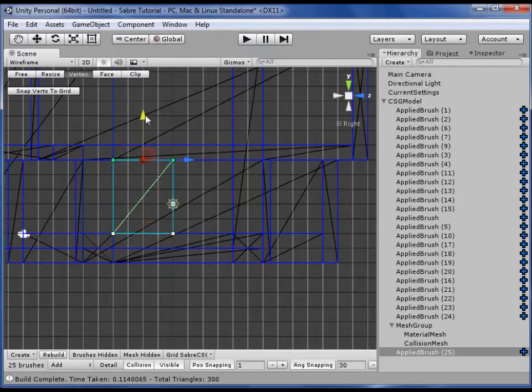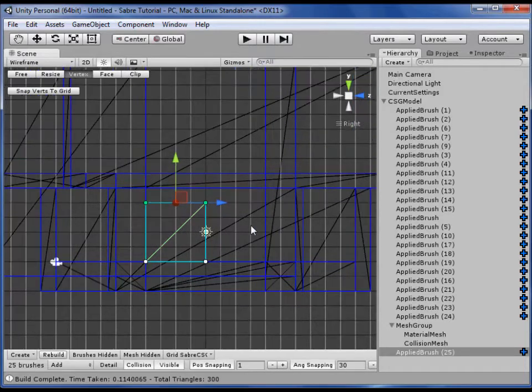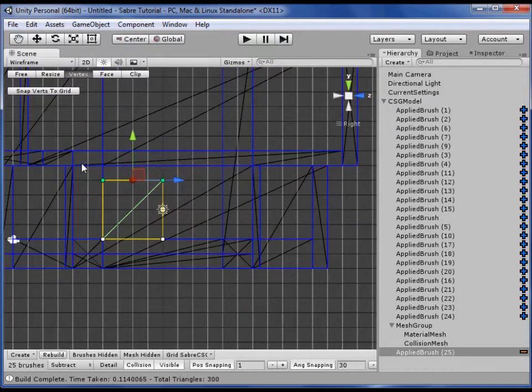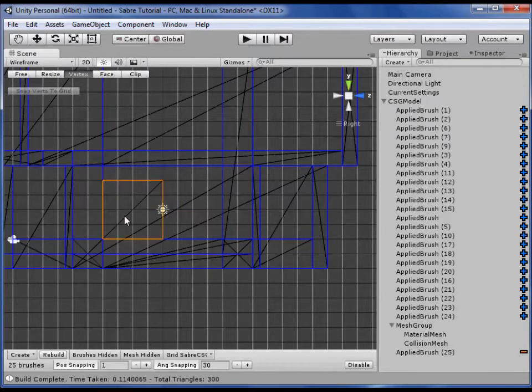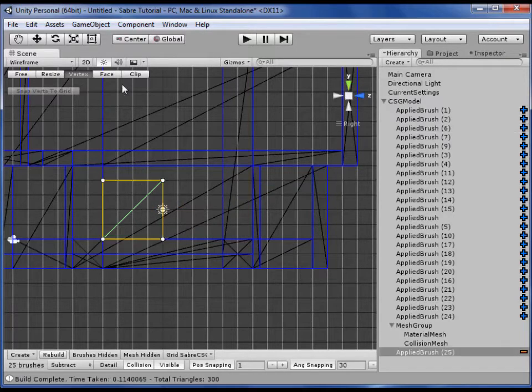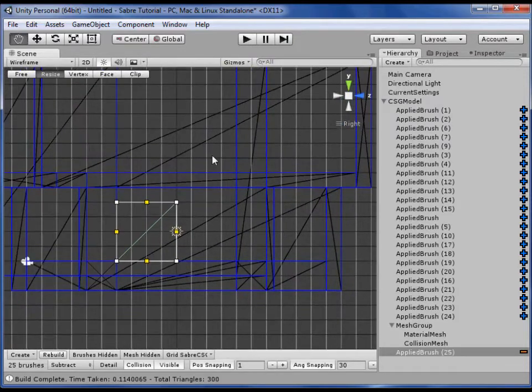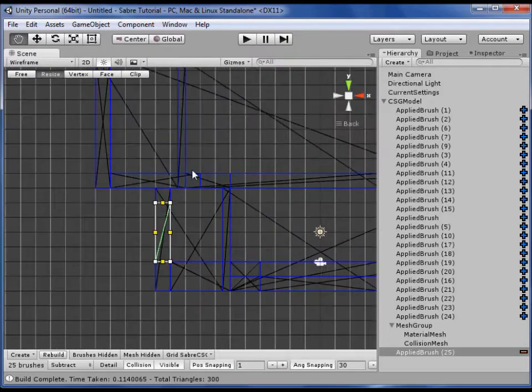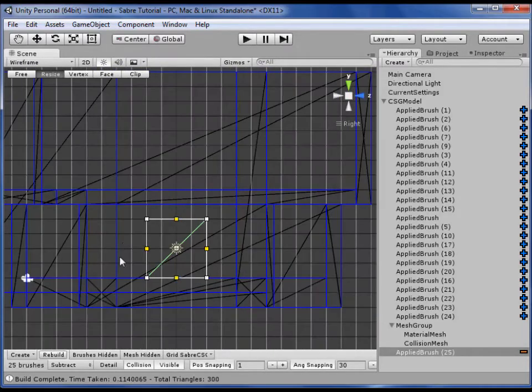Okay, let's make this door frame 4x4. It's way bigger than it should be in reality, but does make it good for something like Rocket Arena, where you don't want players to have too much of a choke point. And let's make that centered in the wall. And you'll notice that I did switch it to subtractive mode just by using the keyboard shortcut S. You can switch back to additive with A and subtractive with S.